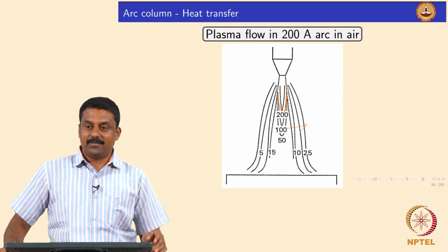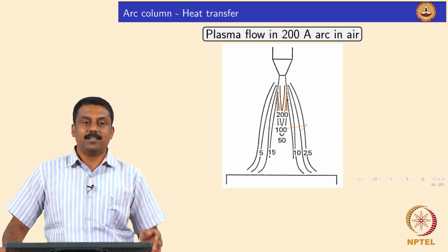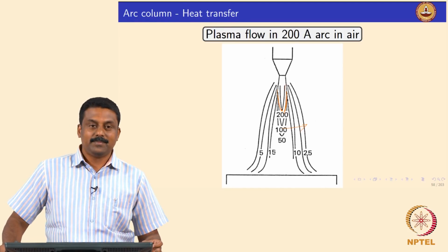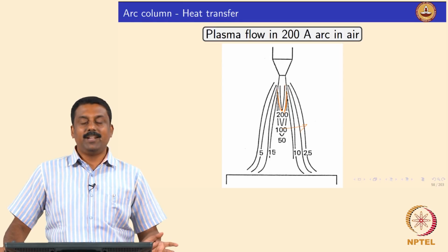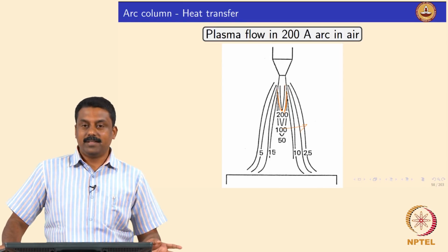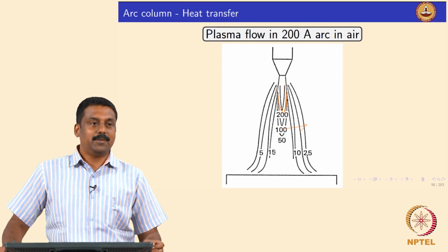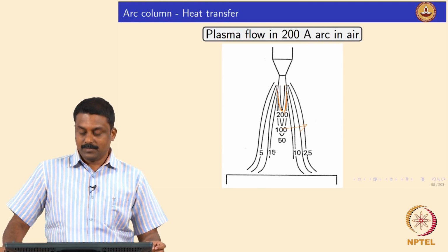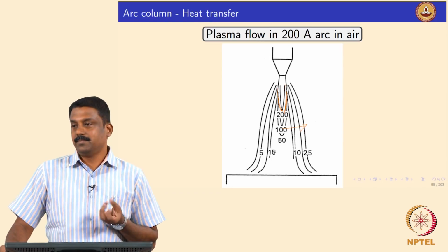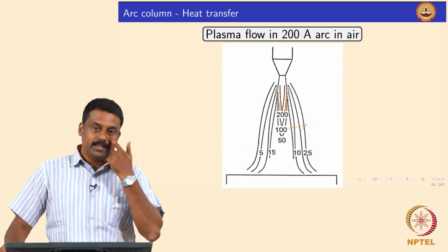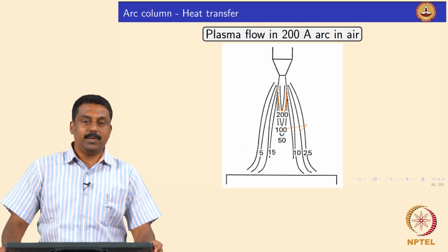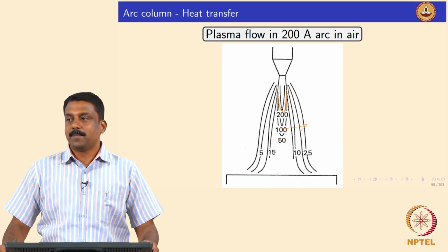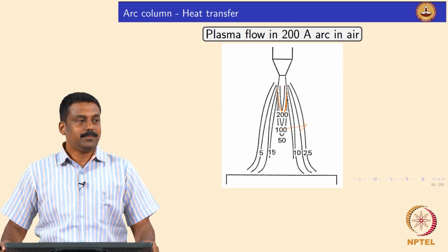That is the conduction heat transfer, how the heat is transferred in an arc. And then radiation heat transfer is by the Stefan-Boltzmann law. And then convective heat transfer, two types: by buoyancy flow, and by plasma jet formation due to the Lorentz force creation. The charge carriers repel when they are placed together, creating a jet force.